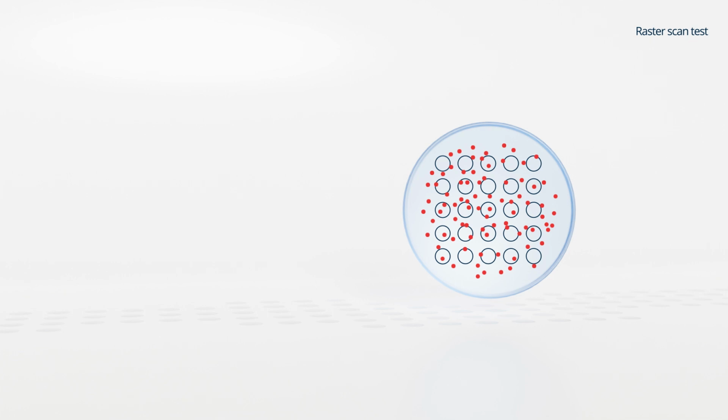For high-quality or very large objects, the defect density is rather low. Accordingly, when using a small laser beam, there is a low probability to hit at least one accidental defect. This is a primary cause of why the laser-induced damage threshold is overestimated or not repeatable on large optics when using a classical test. The raster scan procedure should be applied in such cases.